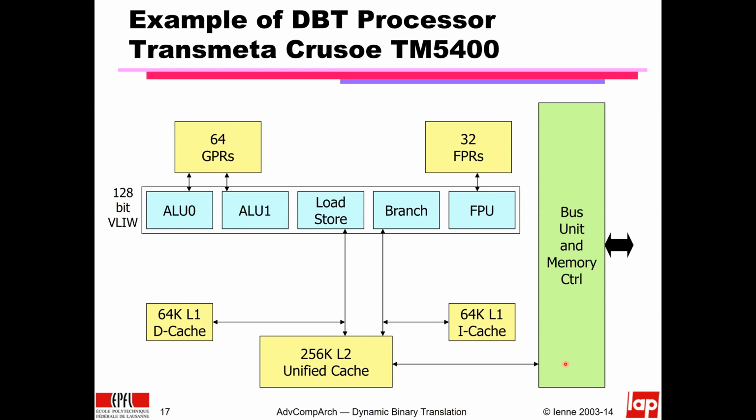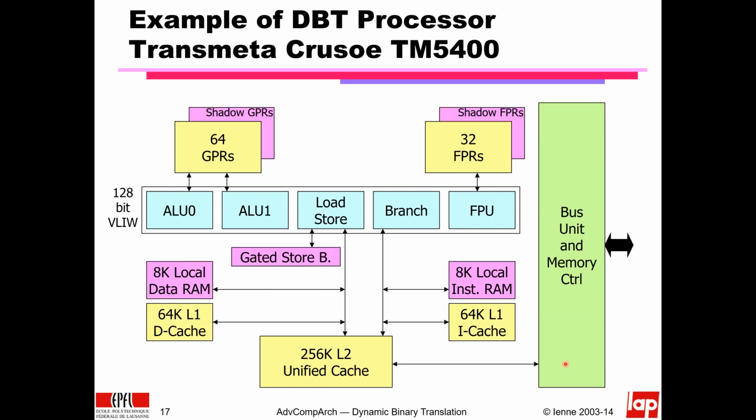And here you see it, right? It's a 128-bit very long instruction word with 64 general purpose registers and 32 floating point registers, the FPU and so on. So nothing surprising, the kind of thing that you want, with a few add-ons that don't necessarily belong to the basic VLIW. Two of these things are easy to imagine: there is some local data RAM and some local instruction RAM, right?